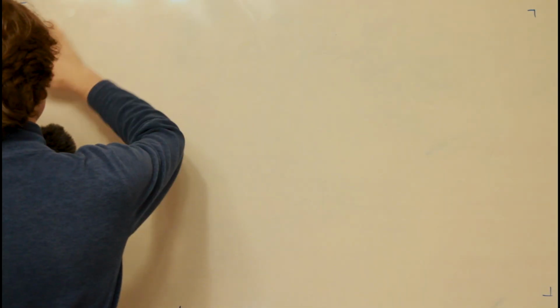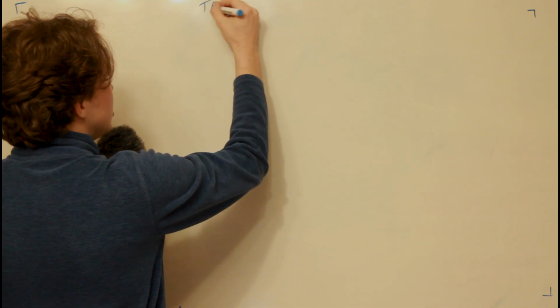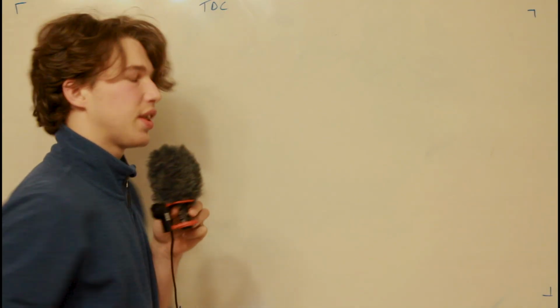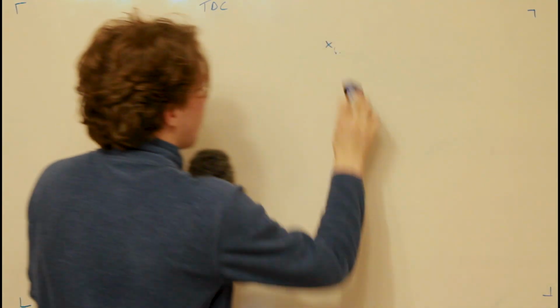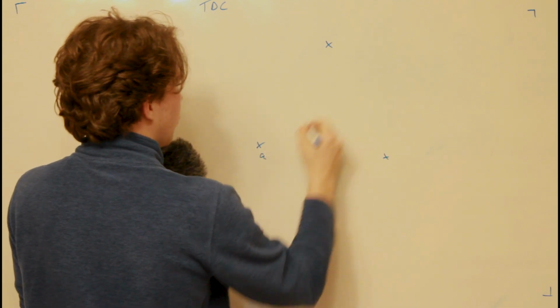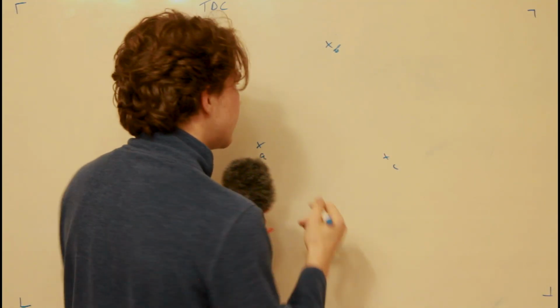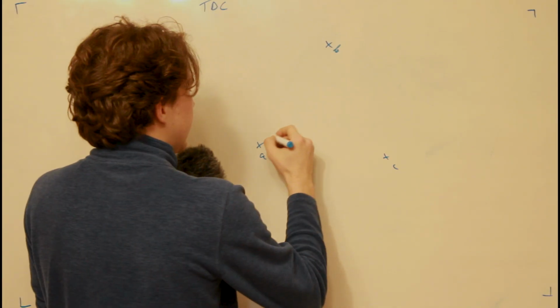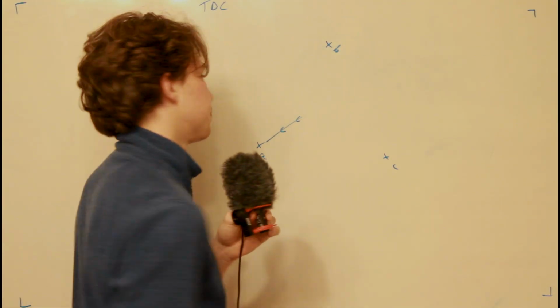So before we start calculating our movements, we first do the calibration. And the calibration is what I call the TDC, torque-driven calibration process. We do this by making one motor a main motor and the others slaves or followers, and let our one motor produce torque and move.